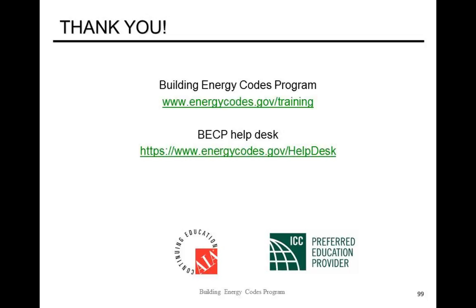We don't call it commissioning, we call it functional testing for various reasons, but there is a relatively large functional testing section for controls in the lighting section. It basically looks at the common controls, occupancy sensors, daylight sensors, and specifies what has to be checked to verify that they are working correctly. There are actually some step-by-step instructions in there, so it's fairly detailed. And yes, those are in there with the recognition that that's a very important part of making sure that you get the energy savings from controls.